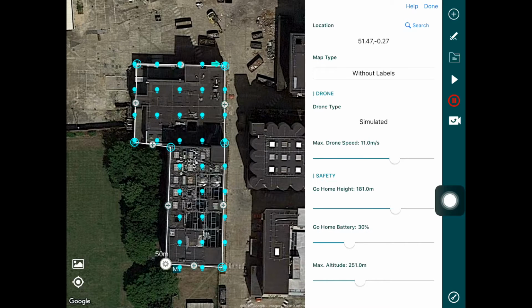So this one's quite important. If you're flying a roof inspection mission, you'd want to make sure that the speed is optimal. One of the things to remember, since this is an inspection mission as opposed to a mapping mission, the drone is going to fly from point to point, stop, take a picture, and then carry on. So the flight speed is not incredibly important in the sense of avoiding motion blur or avoiding camera trigger interval problems that you encounter in a mapping flight. It's more to understand what might be a good speed that you're comfortable flying at. We would recommend going for something between 12 meters per second to 15 meters per second, as you'd like to capture the data fairly quickly.